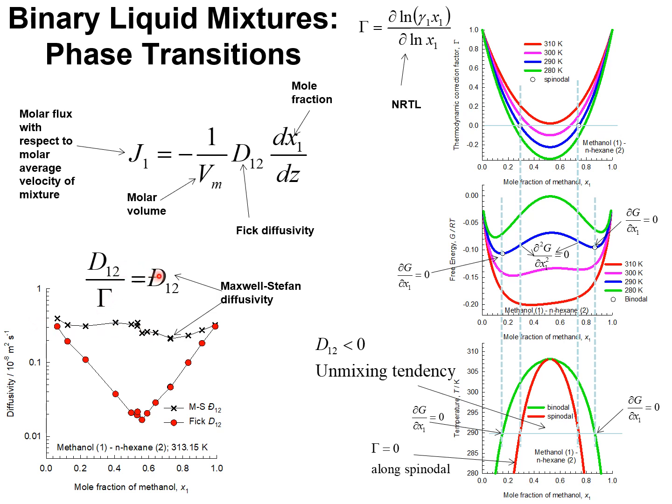This is the persuasive advantage of using the Maxwell-Stefan formulation, because it shows a more predictable composition dependence than does the Fick diffusivity. Now let's try and understand this reduction in the Fick diffusivity value as shown by the experimental data.